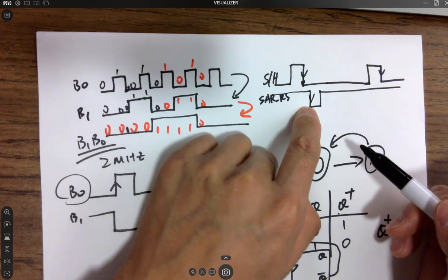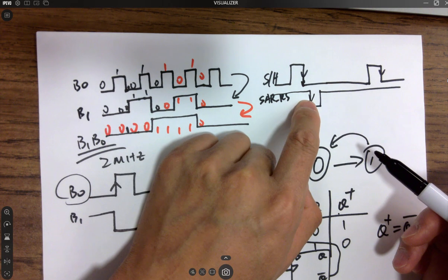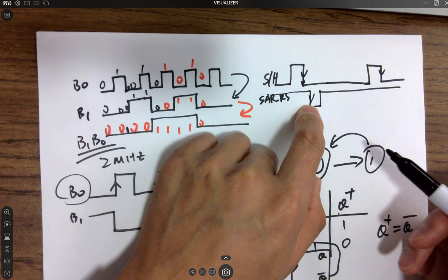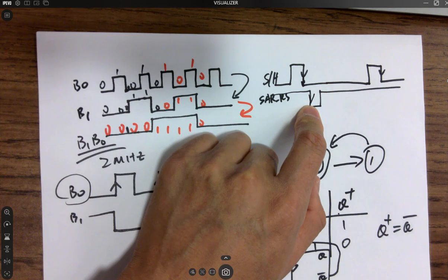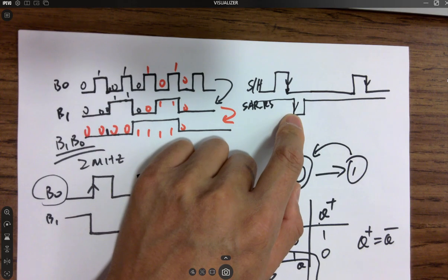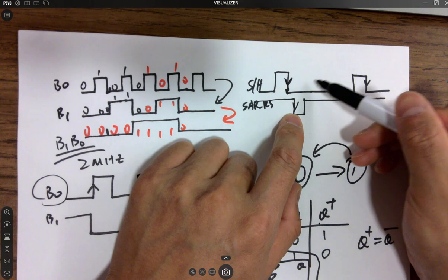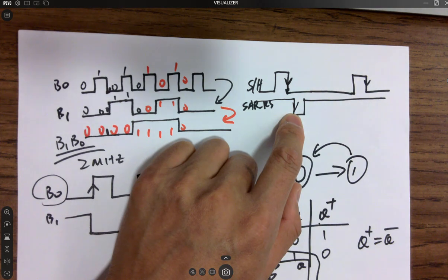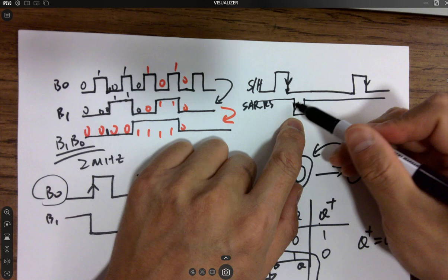So this falling edge is active 0, so that's why this 0 will set the first one, but reset all the following ones to give you the 1 and all zeros, right? Give you 1 and all zeros. And after this falling edge, you couldn't see it from the digital waveform, but the analog voltage is being held over there. It's ready. Okay? So then you do this,